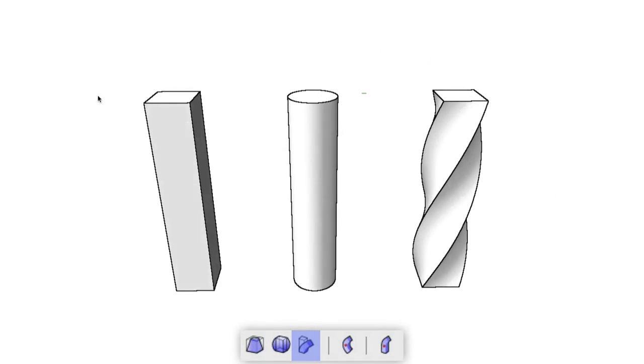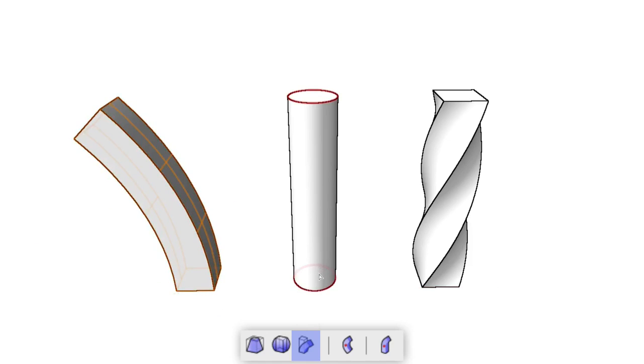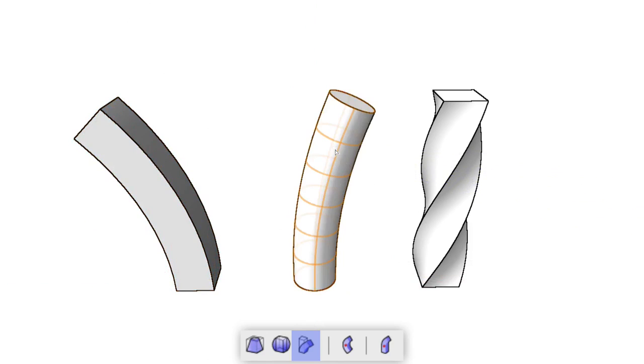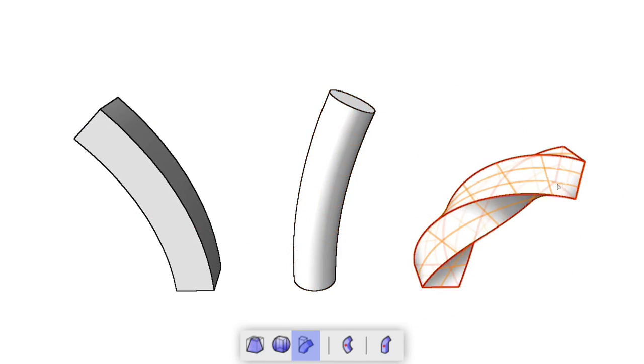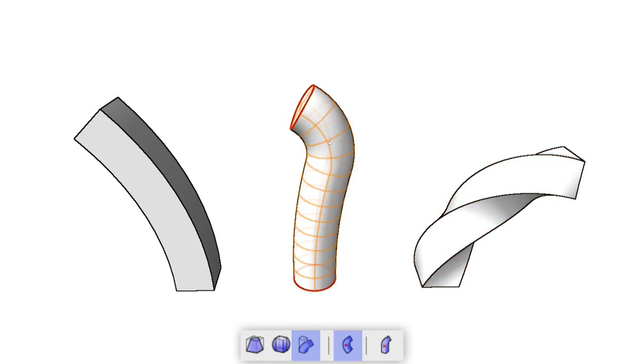Previously, the only way to create an object with multiple turns and bends along it was an extrude-along path. However, it was difficult to use if you weren't sure how much of a bend you wanted or needed before you drew the path object. To fix this, we've added the Bend Solid mode to the Deform tool. This tool allows you to select already existing 3D geometry and bend it via an easy-to-use graphical user interface. Unlike the previous two modes, Bend has another controlled mode, Finite Length, which we will cover shortly.